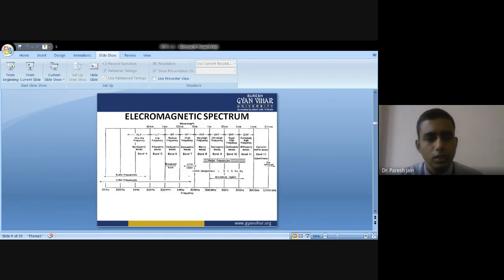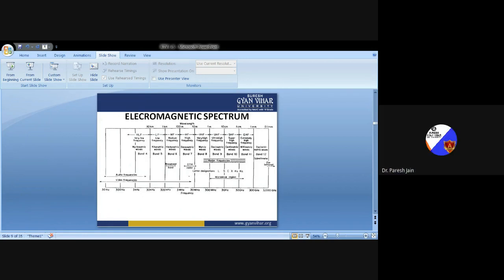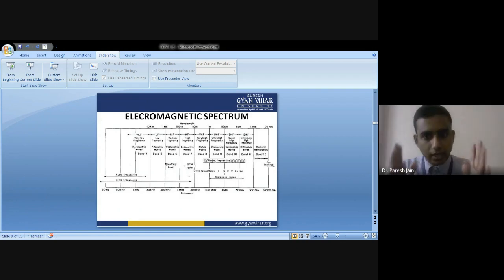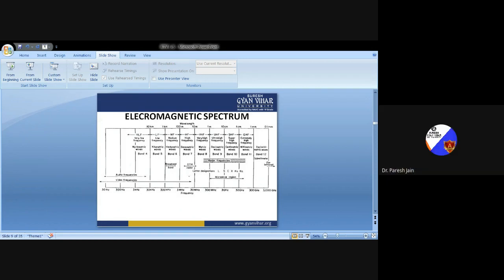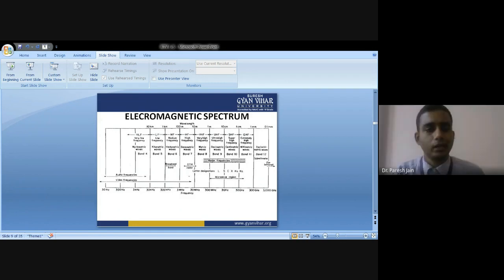Second question: a shipboard radar has a 1 microsecond transmitted pulse width. Two small boats in the same direction are separated in range by 100 meters. Will the radar detect the two boats as two targets? Solution: radar range resolution. The range resolution of a radar is its ability to distinguish two closely spaced targets along the same line of sight.